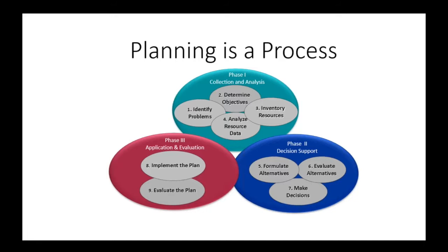And then I guess I jumped a little bit ahead, evaluate the alternatives. So I'm going to choose to do absolutely nothing. What's it going to cost me? I've got gully erosion. It's advancing at 10 feet a year, and it's so many feet wide, so many feet deep. I can figure out maybe my erosion rate is 75 tons per acre. So if I do nothing, excuse me, will this ever stabilize? And if so, when? And how much soil will I lose? So those are the evaluations that we're talking about.